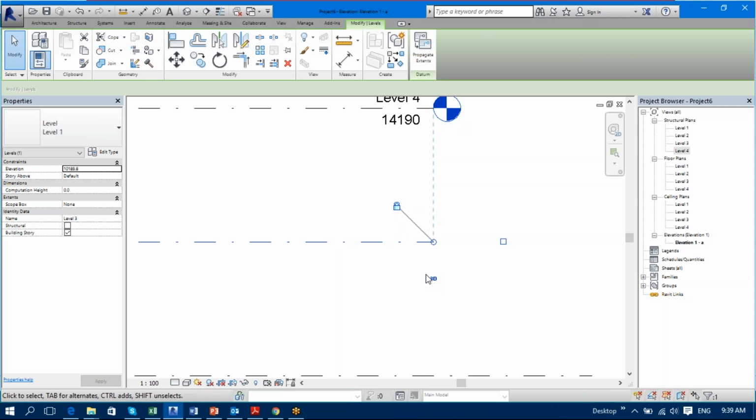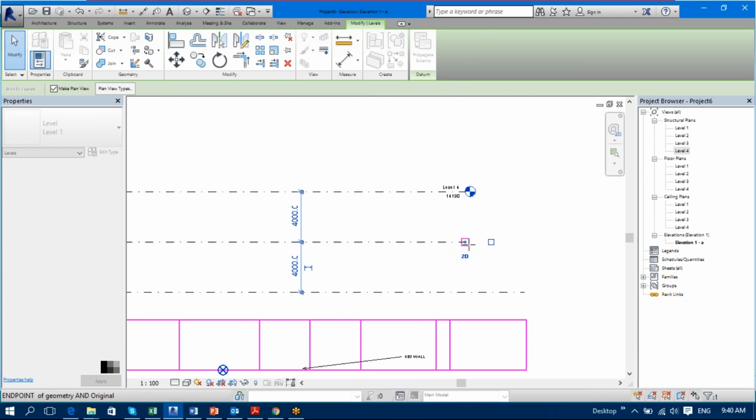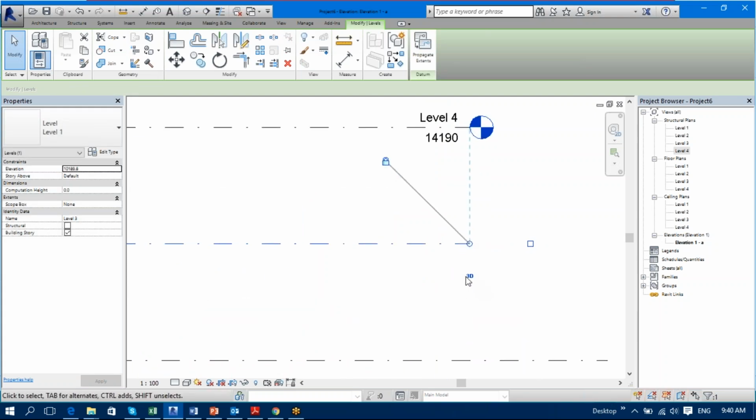So whenever your level is showing 3D, you need to understand that this kind of level will always be shown in this way everywhere. But the moment I select 3D, I just click the 3D part, it becomes 2D now. Now you see, if I change this small part, it is not associated. Understood what happened? The moment I select 3D to 2D, that lock thing disappeared.